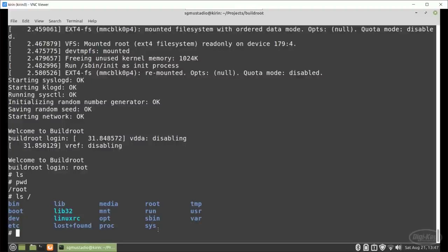You'll probably find that there's no package manager. It's really hard to install stuff unless you bring in cross-compiled binaries. So if you wanted GCC, you'd have to cross-compile it, bring it in, and then build your own programs on this board. But a lot of times what you'll find is you don't want to do that. You want to develop applications on your host computer, test them, and then bring in the binaries to your deployed image file, just because development is faster and it allows you to make an image that can be copied to production, copied to any number of devices that you want.